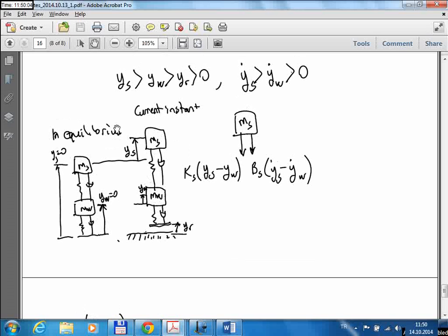Okay, so normally consider that there was no gravity, and the springs, both the spring here and the spring here, will have some neutral length, right? But when you put the car on with gravity, with the weight of the car and the wheel, the spring will get compressed, right? When everything is at rest, the car is not moving.